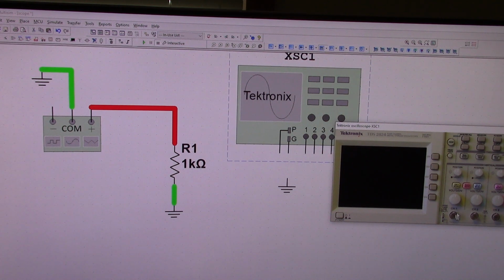By the way, these are called the BNC jacks. So this is like a cable TV jack, you know. Well, not really cable TV, because cable TV is a screw terminal. This is like a clip terminal here. So this is a BNC jack. So there's like 2 pins here, and it'll hold the lead in place. So the ground is this G, and we are only going to use channel 1, so we just connect channel 1 to this power source.